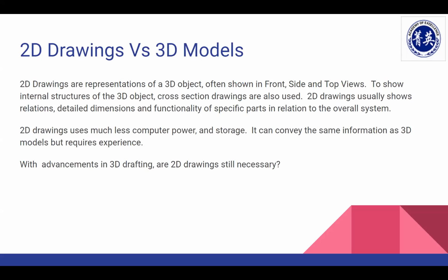But 2D drawings have some advantages over 3D drawings as well. In the 3D drawing, depending on what face you're looking at, it's sometimes difficult to see what the dimensions are, right? Drawings are necessary not just for the designer to know what it looks like, but also for the people who make the parts down the road. They have to know exactly how long a certain line is and how big a certain hole is. A 3D drawing sometimes gets really busy really fast, and since parts cover each other in the 3D view, it is often still necessary to use a 2D drawing to show the exact dimensions of everything you have designed.